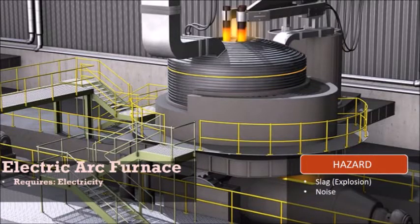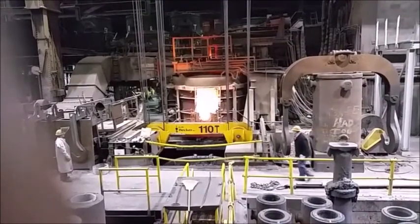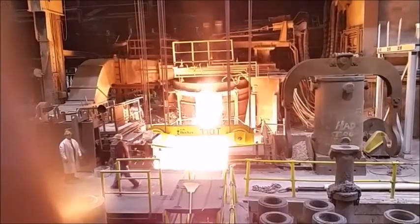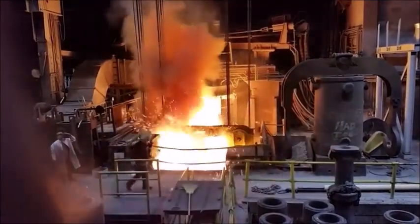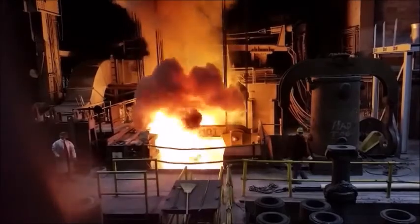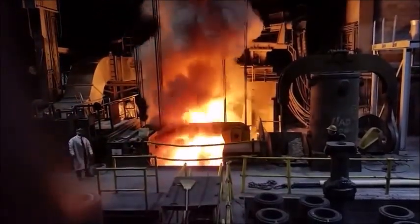In this process, we will be utilizing the electric arc furnace. As the name suggests, it will require electricity. The hazards it produces would be slag and loud noise. The electric arc furnace works by heating charged material by means of an electric arc. The electric arc works by breaking down gas that produces an electric charge. The furnace operations are, in chronological order: furnace charging, melting, refining, deslagging, tapping, and furnace turnaround.